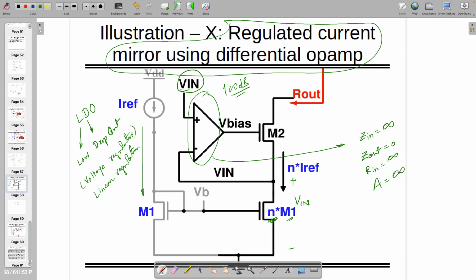So an ideal op amp follows this, but understand that no op amp or circuit exists in this world which is going to have infinity or 0. You have to just define what is infinity, depending on the circuit, as I told you. Anything beyond 1 kilo, most of the time it's high. But if you go to a probe design company like Keysight, they might say 1 kilo is low. For them anything beyond 1 mega is a really good impedance. So it depends. You have to define it according to your need and your requirement, right?